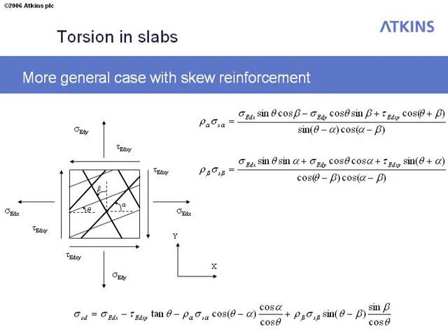With Wood-Armer, we've typically relied on software manufacturers to have that implemented, but we have got a program. I think Tony Smith wrote a program that looked at general moment fields, applied the moment field equations and derived reinforcements. But you have to do that at every single point in your model, so it's not very practical. And this is no more practical because, again, it has to be applied to every single point in your model to derive the reinforcement. So if you're doing a global analysis, you really want something in the computer that does this for you. But to my knowledge, nobody has done that yet.